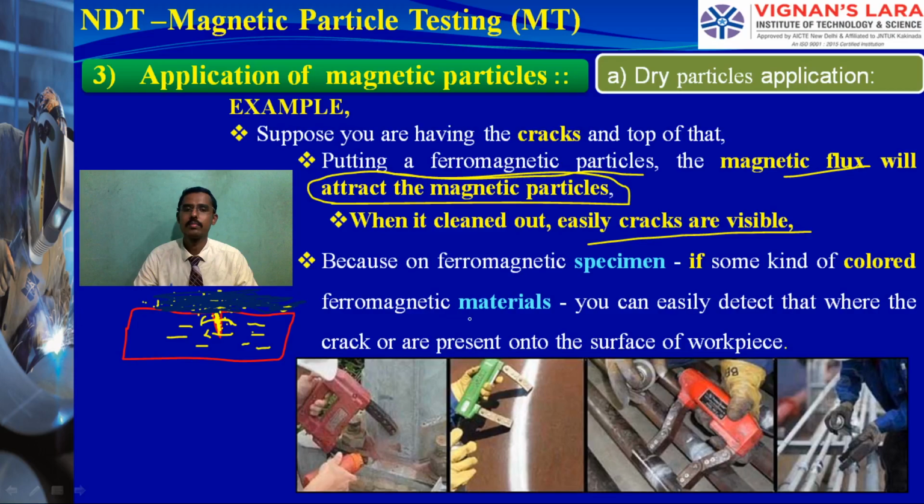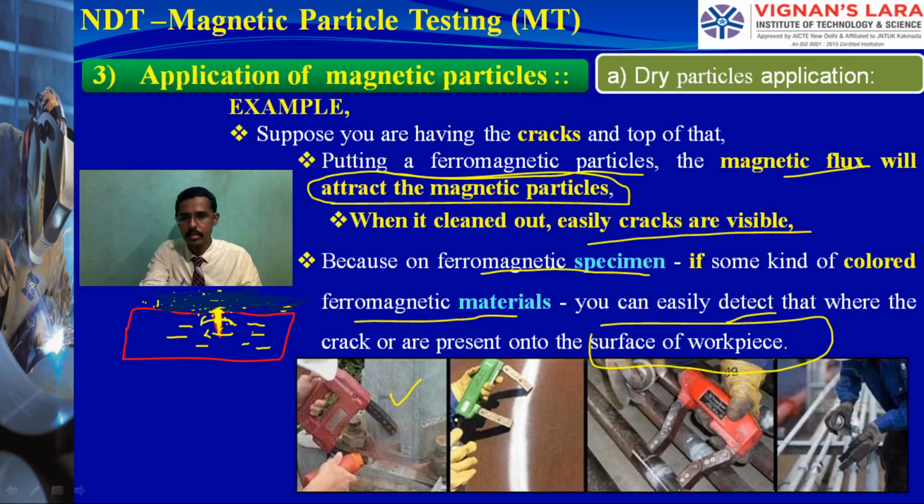See the images. We are applying the yoke method on the weld zone, the weld track lines. They want to find the cracks, so they are showing various images here. You can see how they use this simple method of having a yoke at hand, magnetizing, spraying, spraying, spraying. Likewise, they can easily detect the cracks.